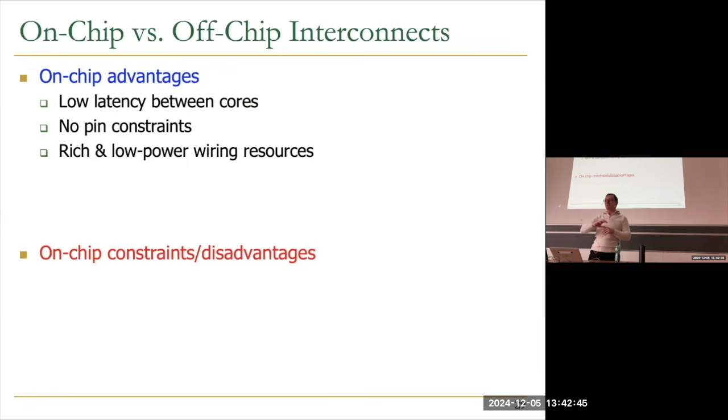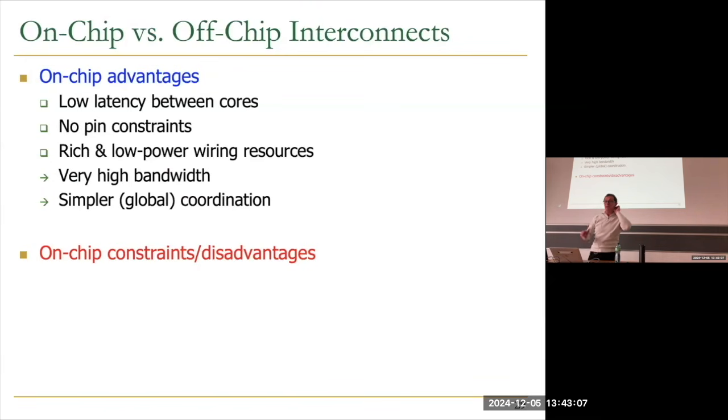Whereas on a processor chip, you have wiring resources. You have multiple metal layers, maybe 14, 15 metal layers. So you can actually put a lot of wires on top of each other, right? With memory-centric computing, I think that also needs to change, as we have discussed. You probably need more wiring resources, but let's not get over there. So on chip today, on compute-centric chips, you have a lot of wiring. As a result, you have very high bandwidth on chip. And if you have a lot of wiring, you can do better coordination. So contrast this with a supercomputer, for example. All of these networks, laptops are connected to a network, right? Internet. If you think about it, the wiring is actually not plentiful on a supercomputer or the internet.